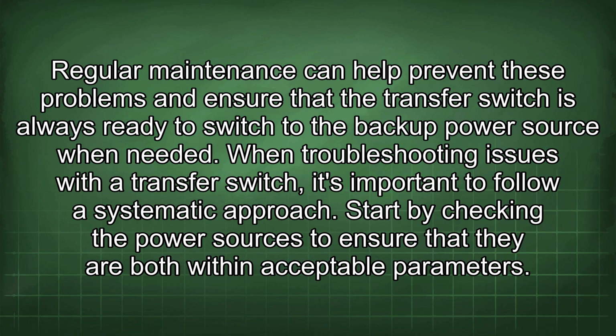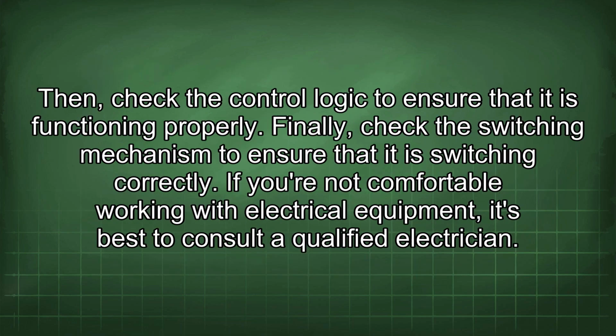When troubleshooting issues with the transfer switch, it's important to follow a systematic approach. Start by checking the power sources to ensure that they're both within acceptable parameters. Then check the control logic to ensure that it is functioning properly. Finally, check the switching mechanism to ensure that it is switching correctly.